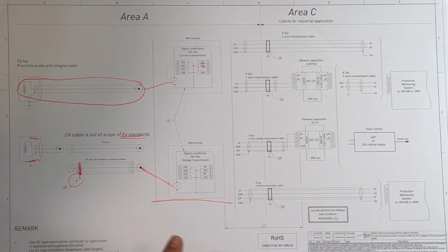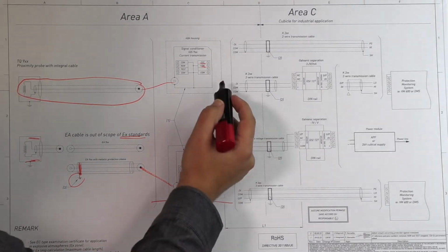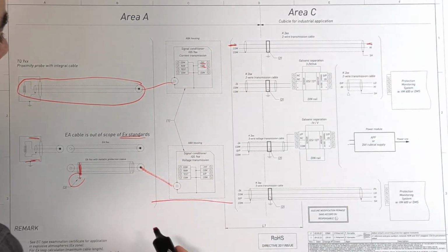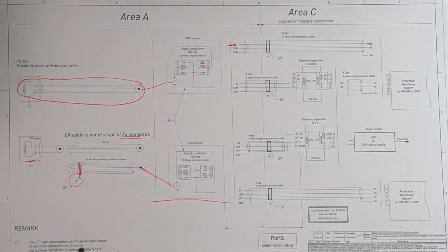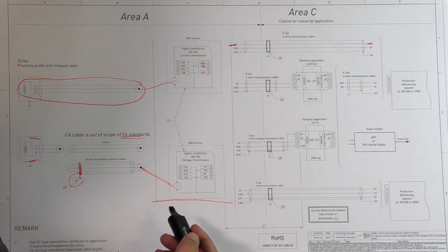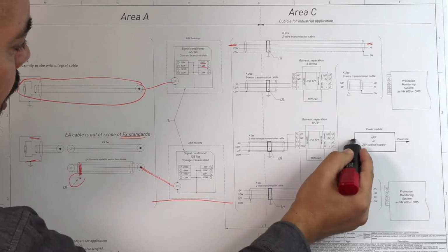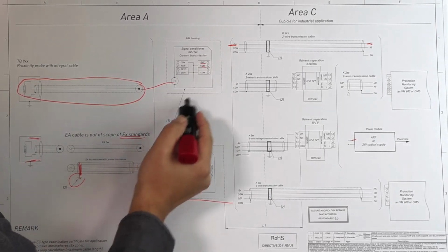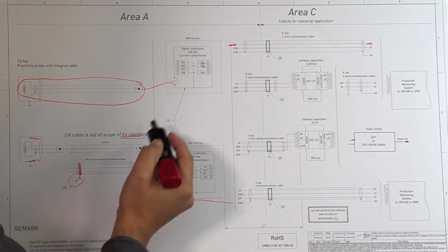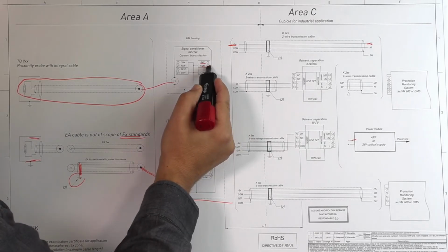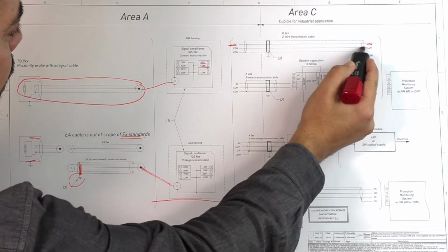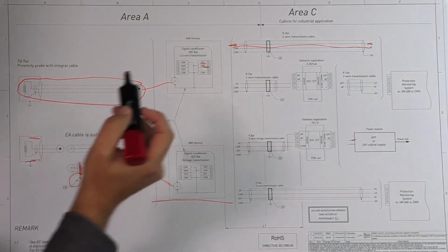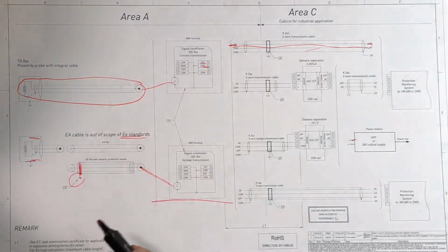Leaving the conditioner, if we have a two-wire transmission cable, you will have the minus 24 volts connected to the sensor power supply of the VMC standard or the MS, or to the negative of another power supply, API power supply, for instance. And the COM, so it's a current mode transmission. You have two-wire transmission cable. So this COM should be connected to the input of our monitoring and protection system, to the IQ input, and should be done by the internal cable in your K2 cable.